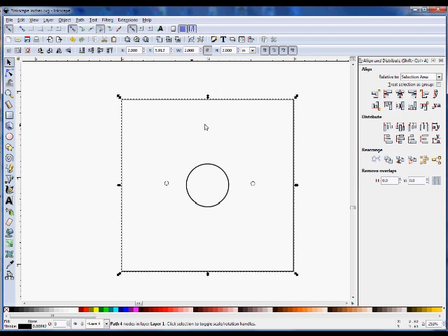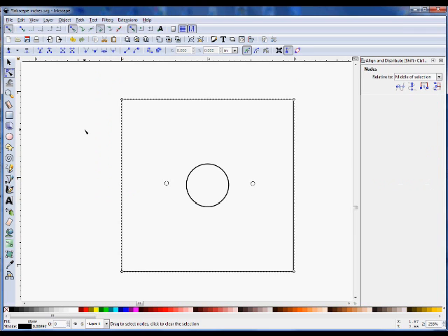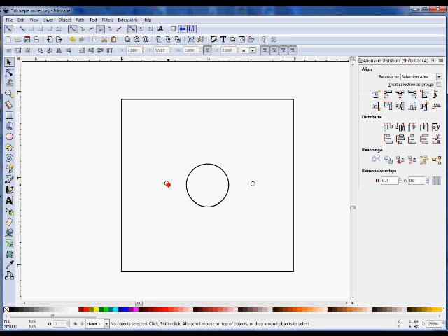If you click on this and go like this, you see it turns red, this turns red, this turns red, and this turns red. So it tells you that they are all paths. So what we want to do now is, again, highlight this one, and we want to bring it down to the size that we want for a PEC, which I would bring down to like 0.2 thousandths of an inch. Since this is locked, it is going to reduce both X and Y directions on it.